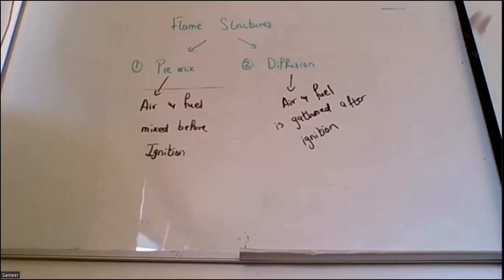Now when this question comes with an assembly occupancy, most of the students think, okay, maybe in the assembly occupancy there must be a different type of criteria, there must be some different readings for the illumination. So they tend to go throughout the book, throughout the whole chapters, and they will not find the answer. In the end, they are wasting their time. Eventually NFPA 1 is very clear about egress lighting. Egress lighting should be 1 foot candle minimum, meaning that when the batteries of the emergency lighting are about to completely discharge, it should still give you an illumination of 1 foot candle. That's the minimum that should be available, right?